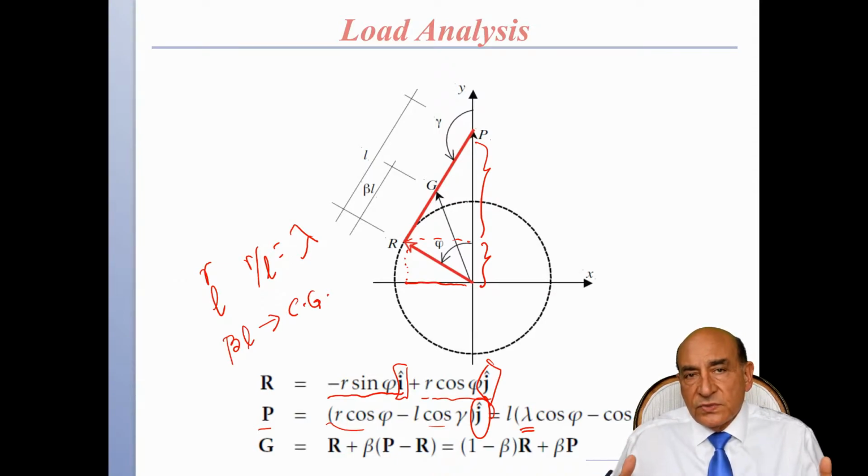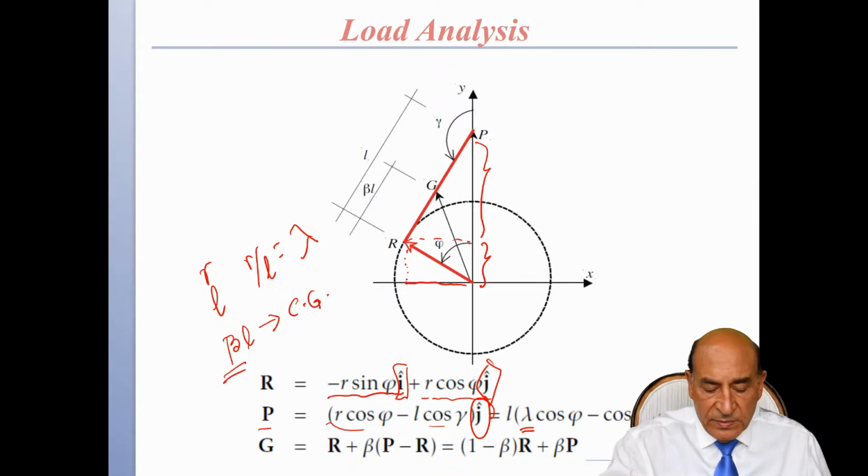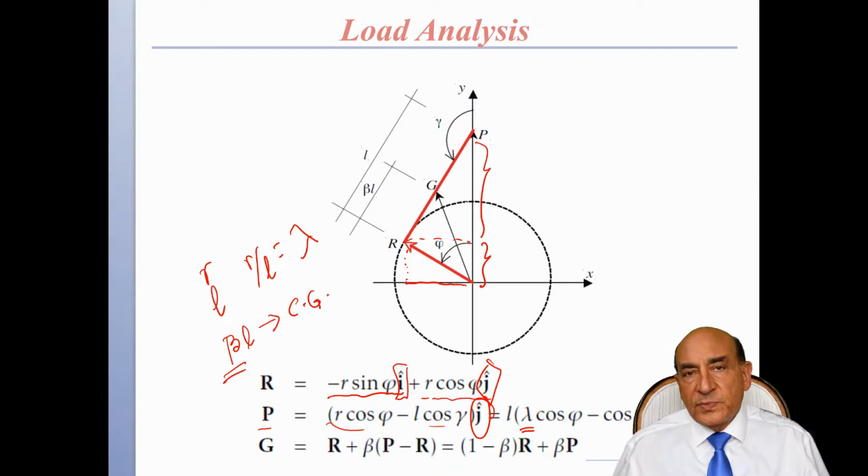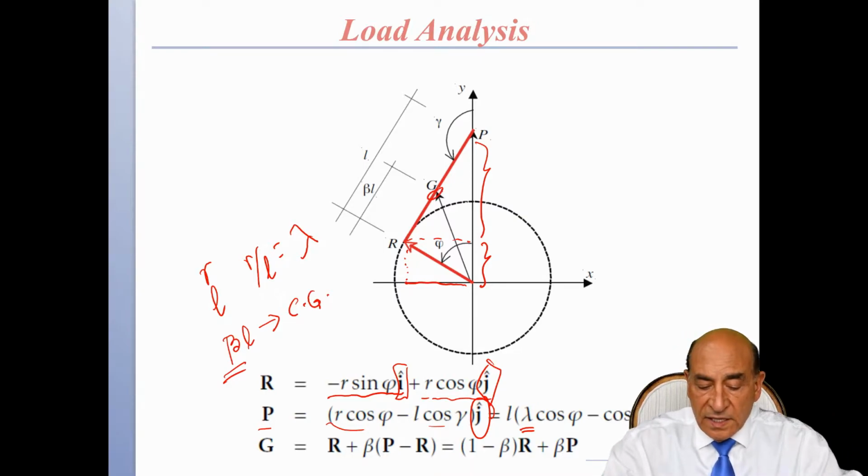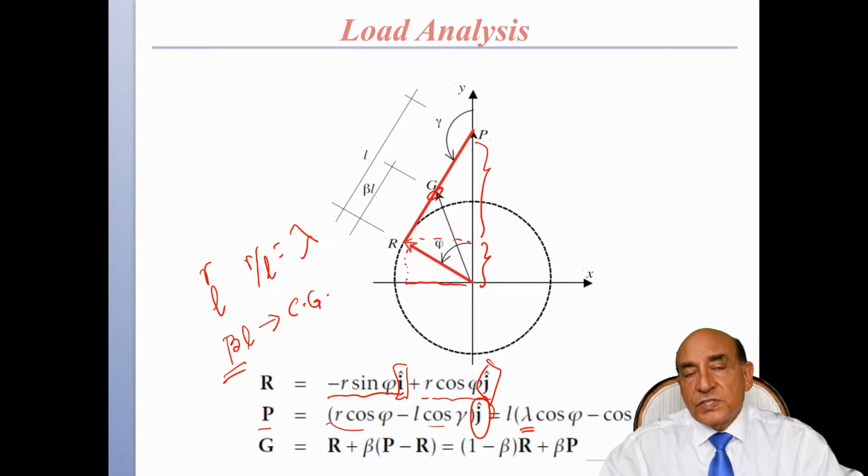And that's important to find out, because as a mass distribution, we will assume that the whole mass of the connecting rod is focused on that point. And that point is described by the value beta, such that when we multiply beta times L, we get the position G, which determines where the center of gravity is,